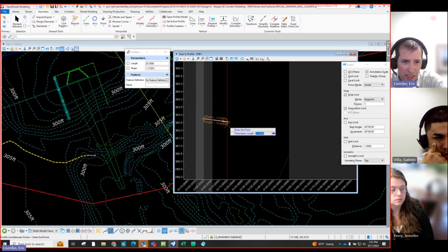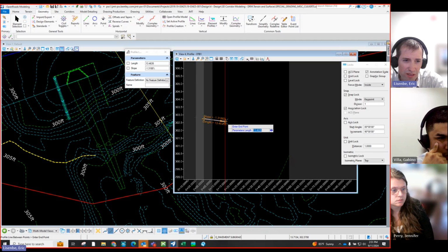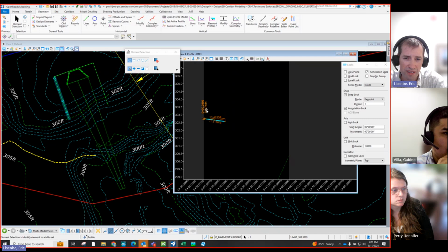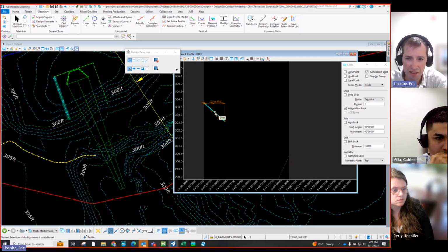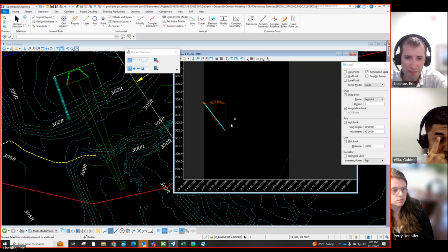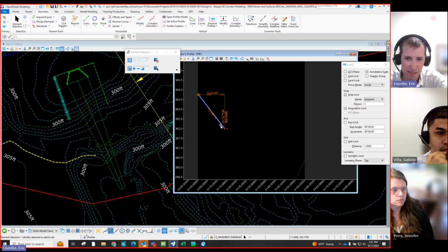But I'll come to here. You have a ditch coming down to my culvert here. If I make that 303.75, hopefully that ties close to the embankment slope. And then this one somewhat higher than our flow line, at like 302. 12% is less than 6-to-1, so that's probably decent.